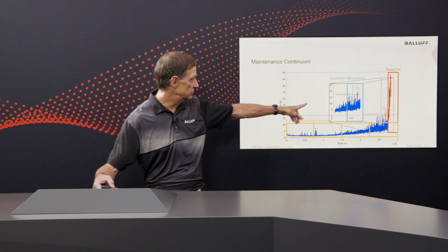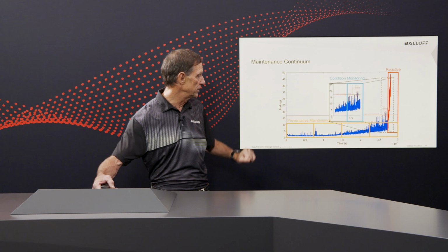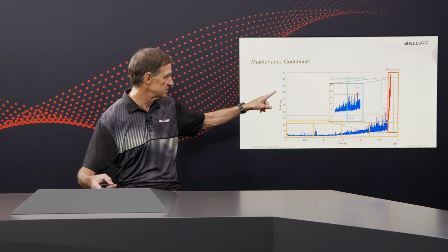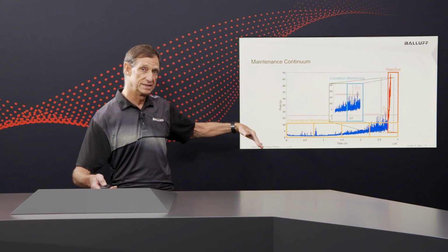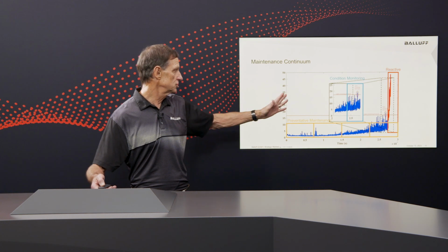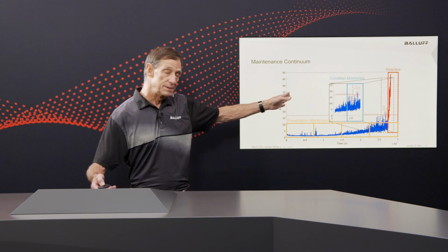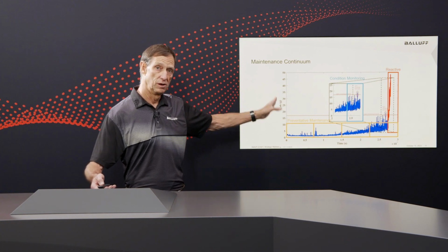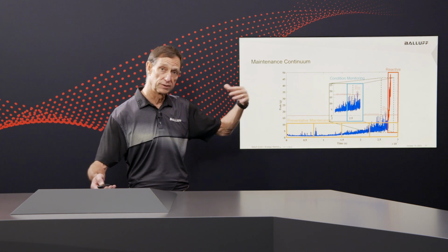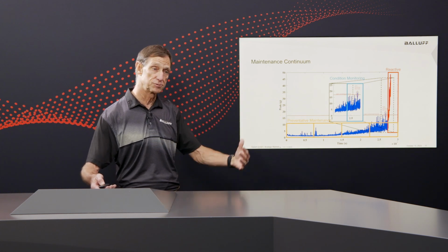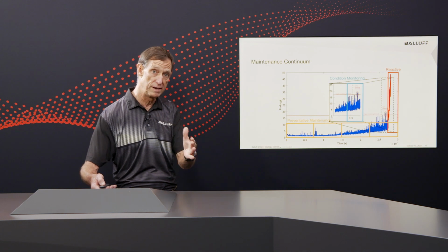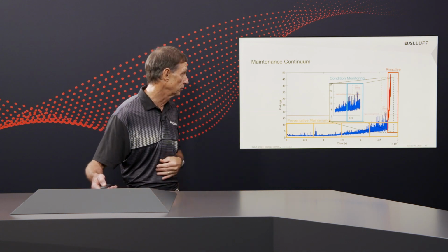You can also see, though, that there were several peaks in the vibration spikes that got close to but didn't exceed the limit. So you potentially could have had maybe 4 weeks notice before the failure occurred to start thinking about looking at that machine, doing an inspection, and start planning your maintenance before the failure actually occurred.